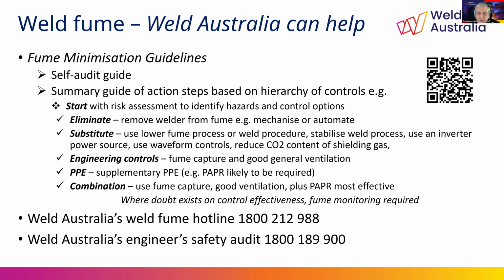Alternative control needs to be considered, which is where the risk assessment is really important. Where there is little evidence of serious consideration being given to the use of fume capture, it is going to raise doubt in the mind of the regulator, and if the inspector comes knocking, they are likely to ask you for a formal air monitoring program to be performed to demonstrate your controls are adequate and both the welder and all people nearby are well protected from excess weld fume.